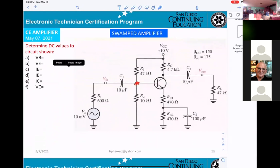And now another amplifier they call it the swamped amplifier. That means they're adding one more resistor here, and a bypass capacitor here that only bypasses RE2, not RE1. Okay. And also they put an RS equals 600 ohm here.